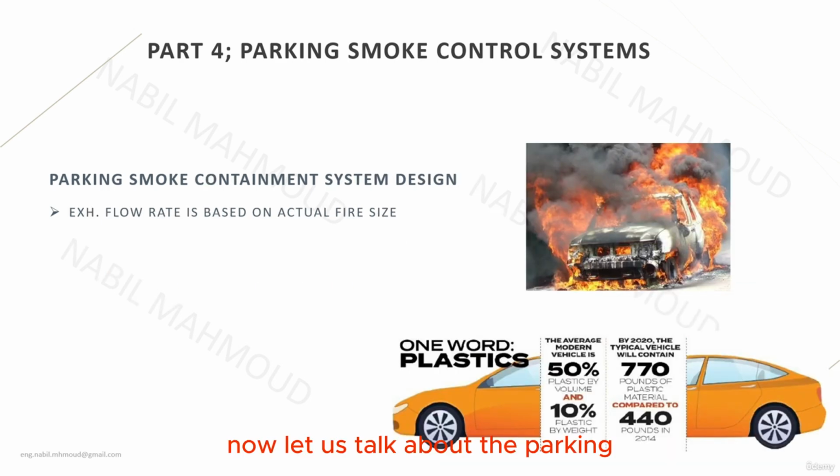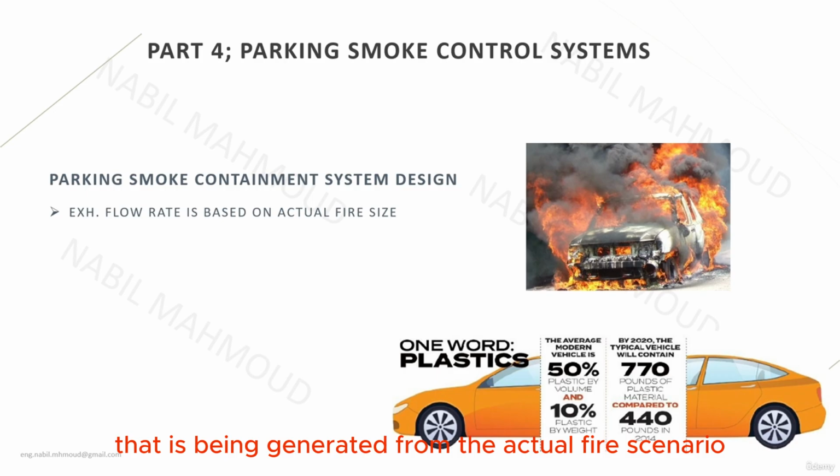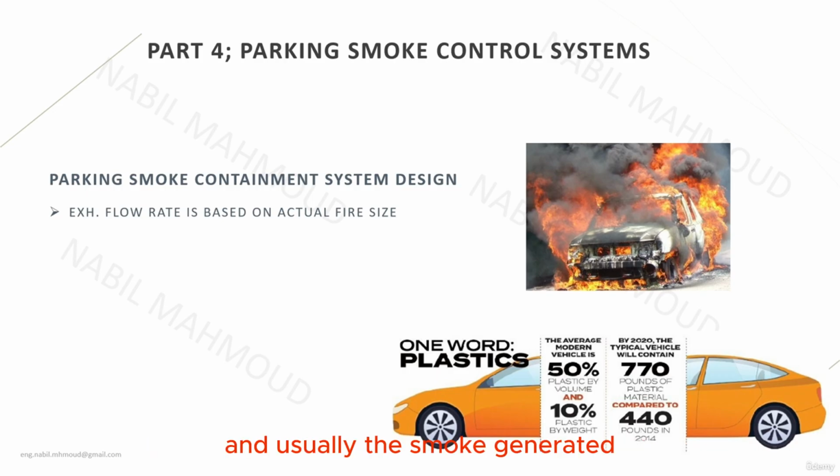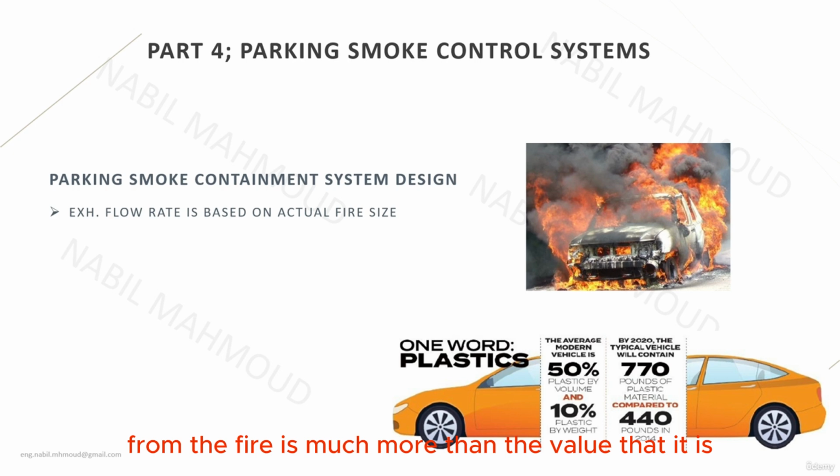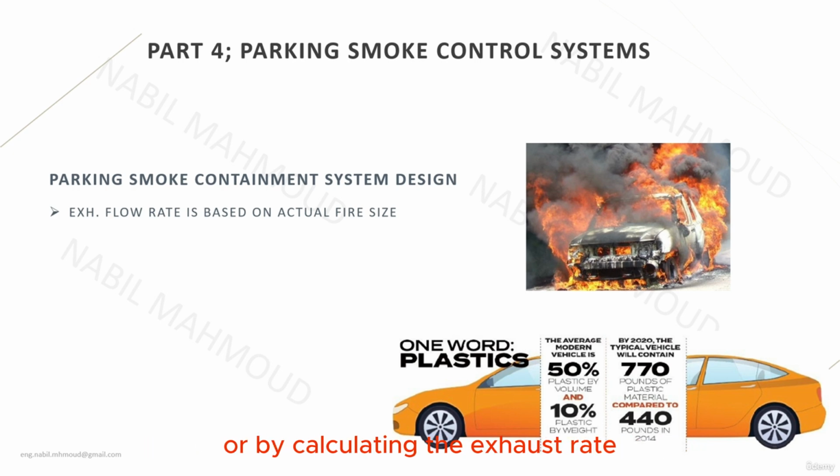Now let us talk about the parking smoke containment system design. The containment system, which is not the management, is the most accurate and the safest system when it comes to sizing the capacity of the smoke exhaust fan, because it is sized based on the amount of actual smoke being generated from the actual fire scenario. And usually the smoke generated from the fire is much more than the value calculated in the smoke management or by calculating the exhaust rate using the air change per hour.